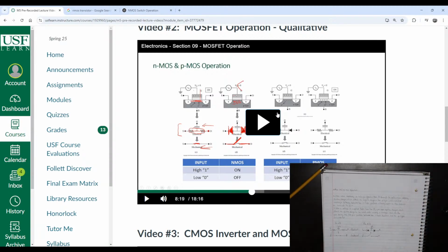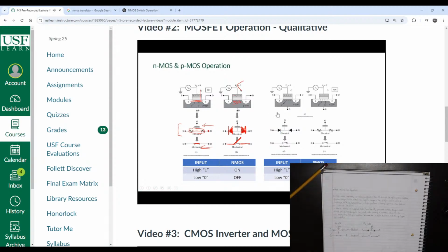And this is probably just the opposite. What happens when you apply positive voltage to the gate of an NMOS transistor? We turn the transistor on. It's this condition here. Positive voltage is our high, and the transistor turns on. When we apply a negative voltage, when we apply a low on the gate, our transistor is off.